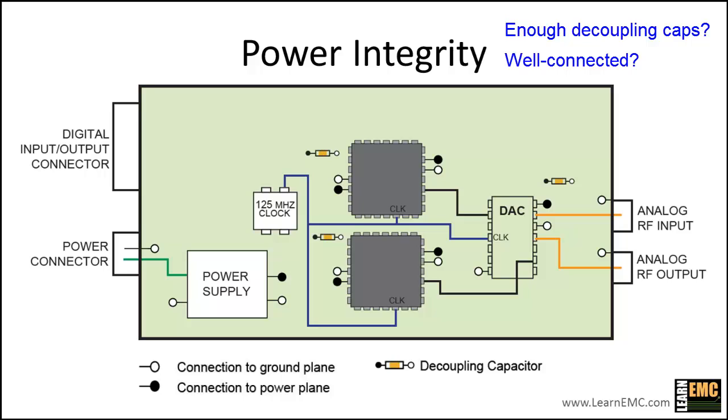We haven't specified the dimensions of this board, but it's likely that there is some overlap between the power bus resonant frequencies and harmonics of the digital signals. Additional well-connected decoupling capacitors will help dampen these resonances. Decoupling capacitors are inexpensive and they don't take up much space, so in the new layout, we'll add several more.